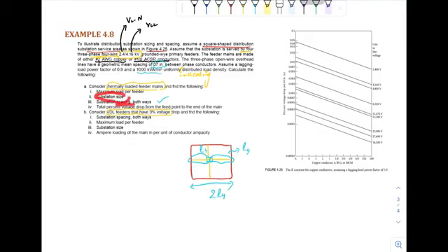Now what is the substation size? Substation size is the total load served by the substation. In order to compute the total load, you should first compute the load per feeder, that is S4, and then compute the overall load, that is the number of feeders multiplied by the load served by one feeder. This will give you the substation size. Maximum load per feeder is this one. This is the substation size in kVA, and this is the spacing of the substation.